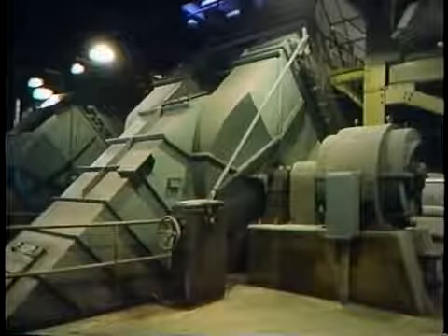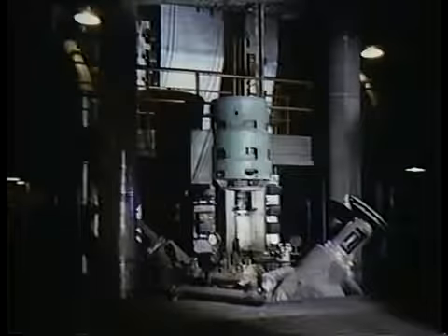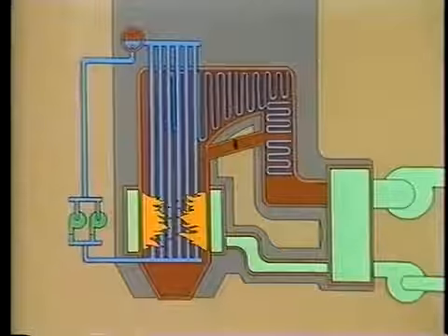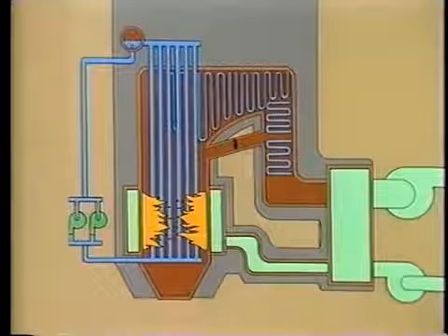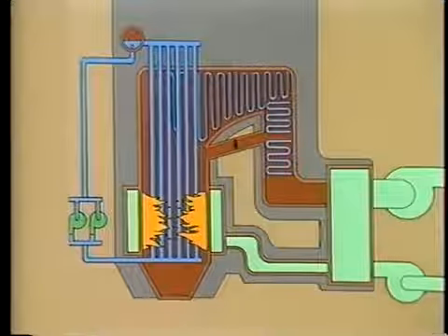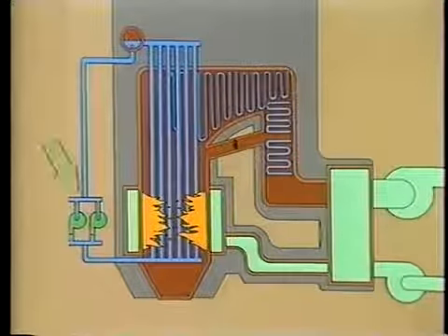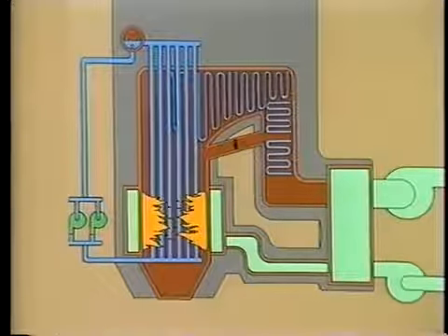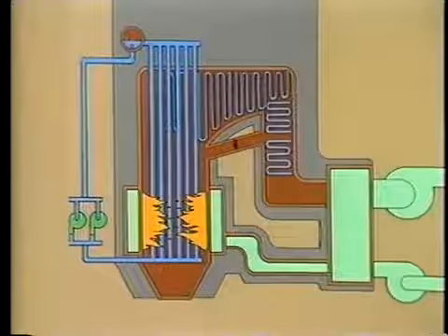The equipment that we'll cover includes induced draft and forced draft fans, air preheaters, boiler water circulating pumps, and boiler feed pumps. In general, the auxiliaries that we've mentioned are arranged in pairs, such as these boiler water circulating pumps. Each component in the pair is capable of handling at least 50% of the normal load.